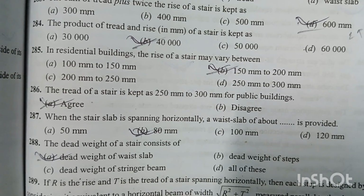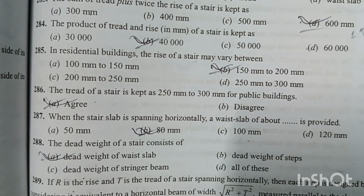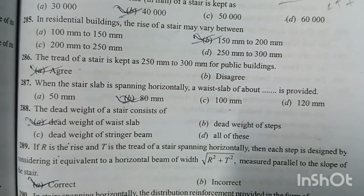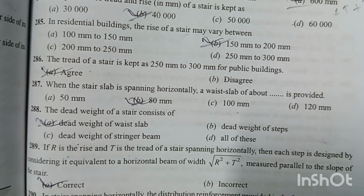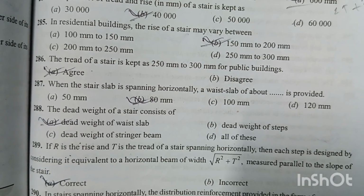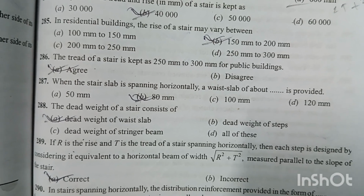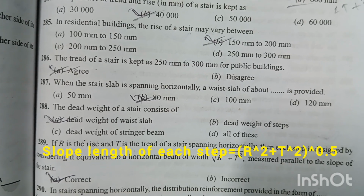Question number 288. The dead weight of the stair consists of dead weight of the waist slab. Option A is right answer. Question number 289. If capital R is the rise and capital T is the tread of a stair spanning horizontally, each step is designed by considering it equivalent to a horizontal beam of width root over of R square plus T square measured parallel to the slope of the stair. Option A is right answer.